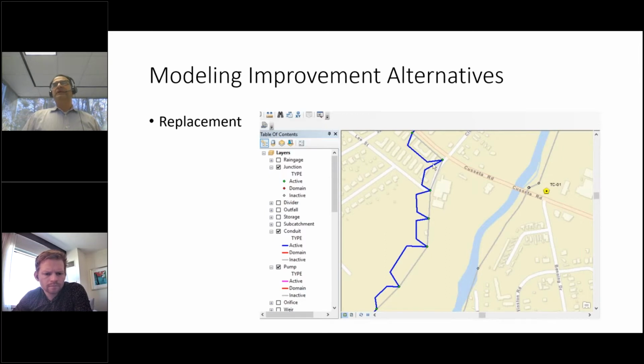Or in some cases, another trick I learned from a colleague is you have your original pipe and then you start drawing pipes that connect to the same node. What's nice about this is you can force the length to be the same. The pipe is obviously graphically longer, but you can type in the length to make sure it's the same, and at least you see the two options in front of you. One is deactivated and one is active.